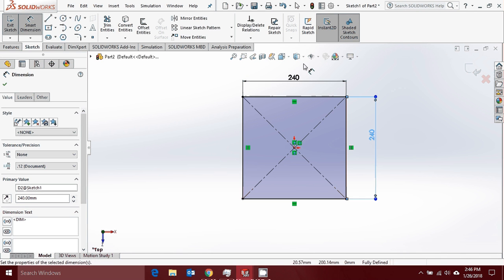If you haven't already, you should ensure that your modeling setup is in millimeter units rather than inch units. To do that, at the bottom right here we have a drop-down menu that offers different standards of unit measurement. We'll use millimeters, grams, and seconds, so MMGS, which you will always work with when you're working in this class. So just quickly switch it to MMGS if you haven't already, and make sure that your dimensions are all in millimeters. So here we have 240 by 240.